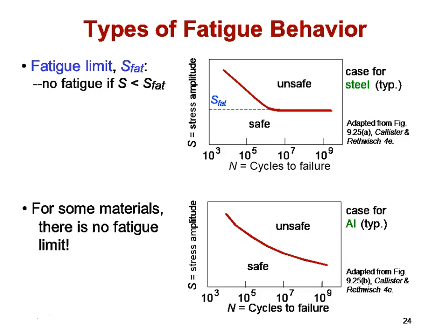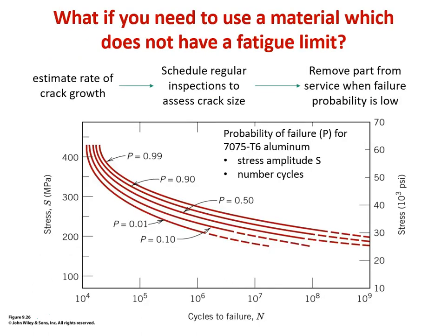And when these materials are used in cyclic loading, which again is almost any application, they have to be frequently inspected to make sure that we're not getting fatigue-driven cracks that could be getting close to what our K1C limit would allow for the given material's fracture toughness.